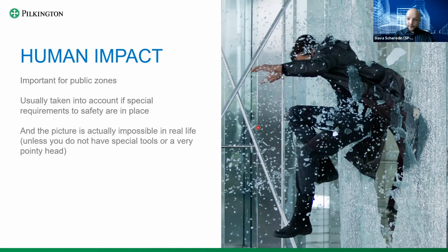For Europe, we are using European norms, and we are deriving the basic climate loads from the website. For example, for Singapore, we're using ASHRAE. For Australia, ASHRAE 2 and NFRC. So everywhere we're trying to use local norms for estimation of wind loads.